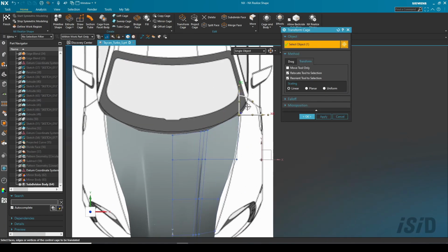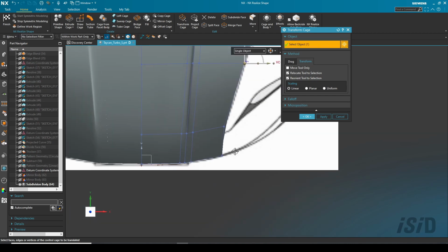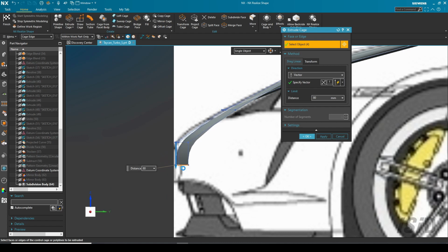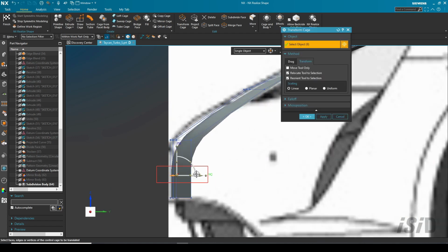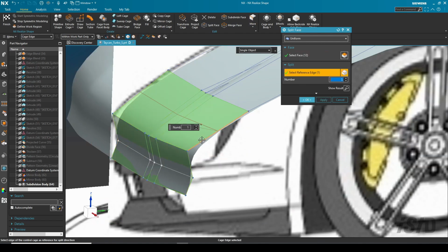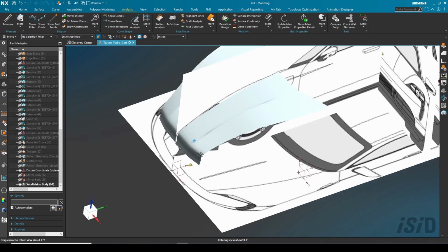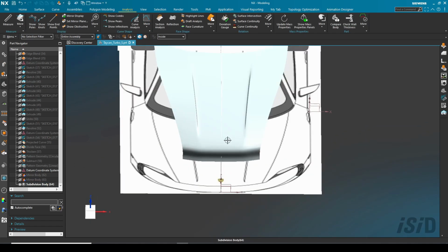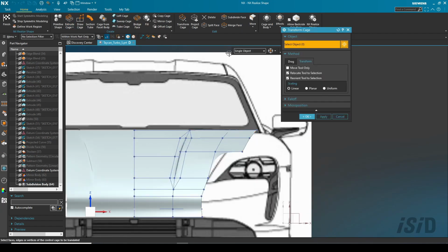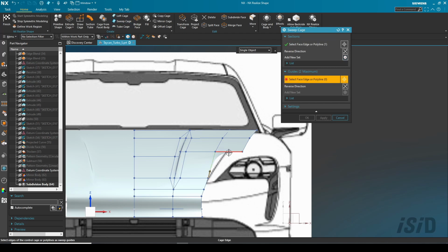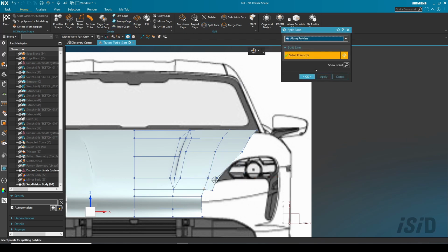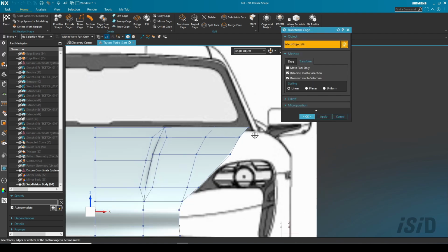And I add or refine more shape again using transform cage, and this one is for adding more surface by extruding some cage edge downward using extrude cage. And again I add more refining shape using a combination of transform cage and extrude cage.